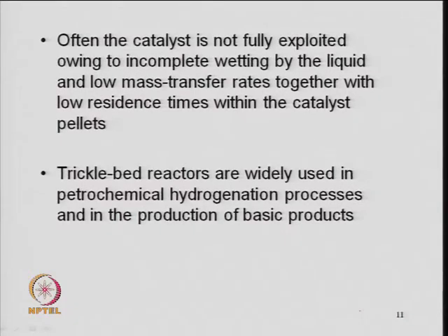So, depending upon the hydrophobicity or hydrophilicity, there will be a kind of wetting phenomena. Wetting you practically cannot identify mathematically, but it is a matter of what fraction of the surface of the solid is being wetted by the liquid, and that decides the efficiency of the process. Sometimes 100% wetting may not be good, and a completely hydrophobic substance is also not good. So, you need a balance to control the mass transfer resistances at the surface of the solid, because liquid and gas have to contact properly in the presence of solid for the transformation of these reactants into a product.